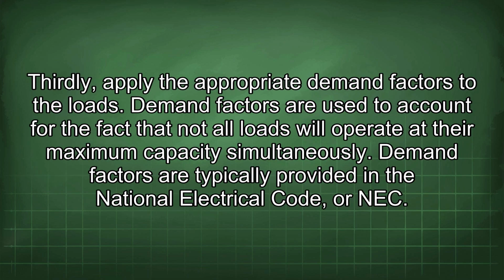Thirdly, apply the appropriate demand factors to the loads. Demand factors are used to account for the fact that not all loads will operate at their maximum capacity simultaneously. Demand factors are typically provided in the National Electrical Code, or NEC.